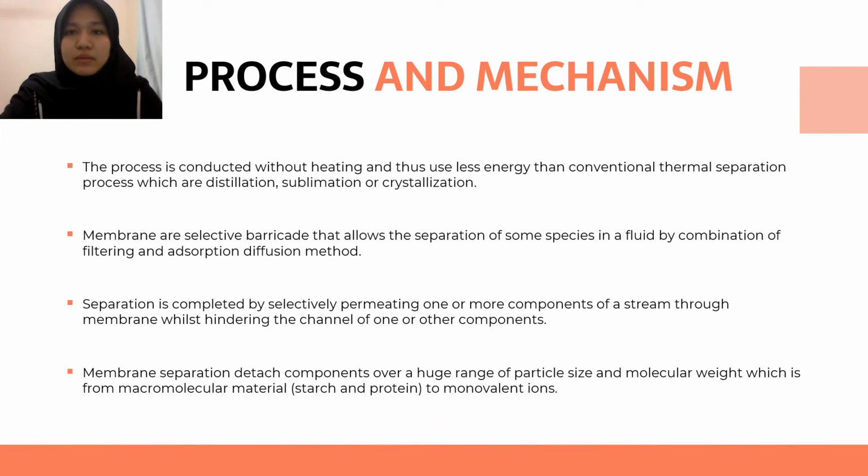Separation is completed by selectively permitting one or more components of a stream through the membrane while hindering the passage of one or other components. Membrane separation also detaches components over a huge range of particle size and molecular weight, from macromolecular materials such as starch and protein to monovalent ions.